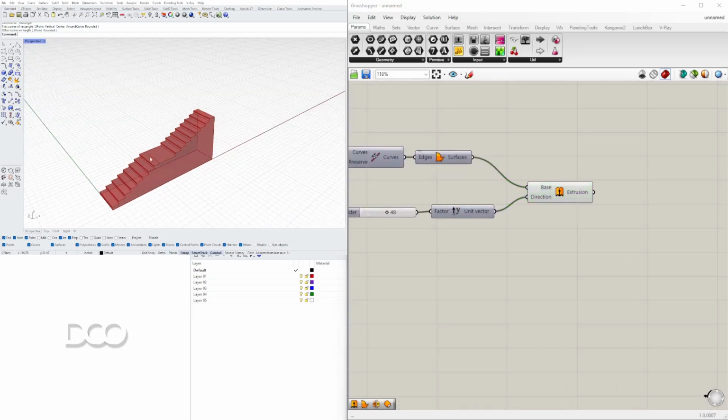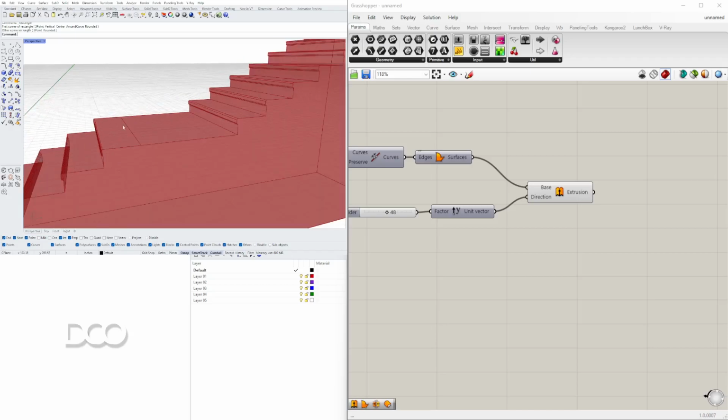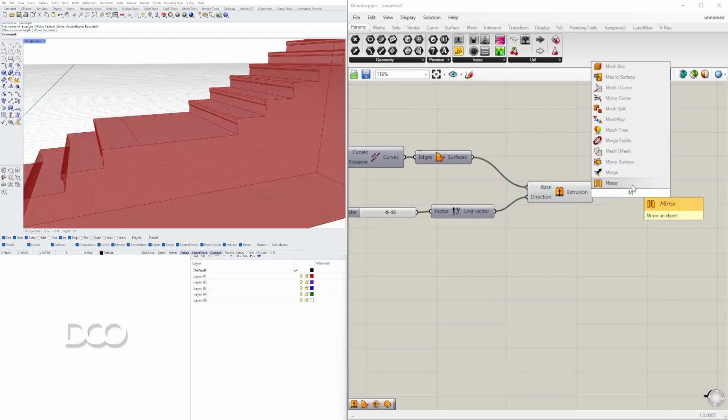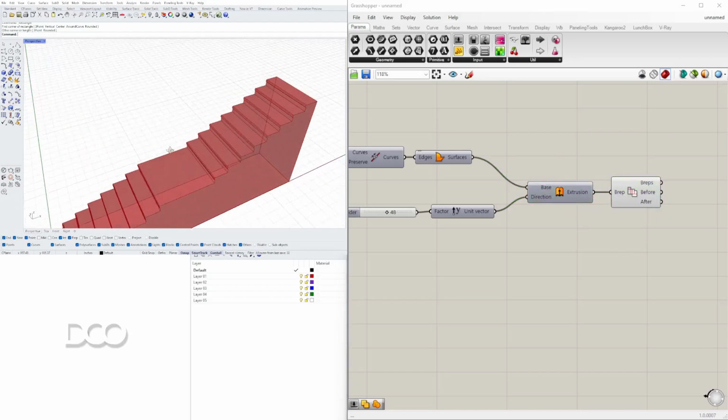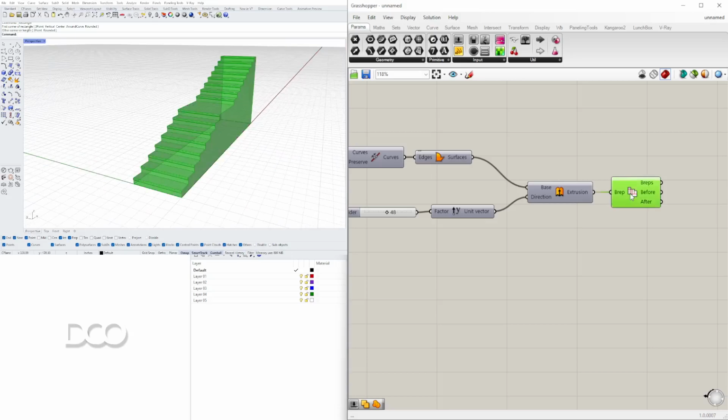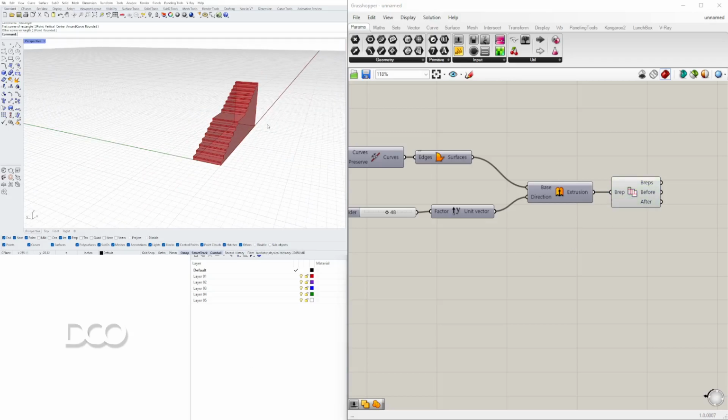And lastly, what I see here is there's this crease, and that's created from that overextension for the landing. So I do tend to go to merge all coplanar faces. As long as we don't have too many, it won't take too long. Sometimes when you bring this in and you have way too many for it to take care of, it does bog down your script a little bit.